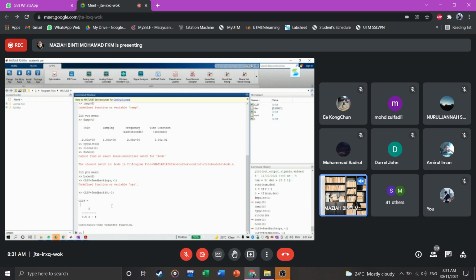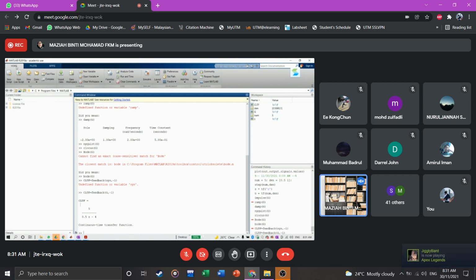So we can draw as if we draw on paper, and then we can simulate the behavior of the system. All right, so in order to open Simulink, you can click the Simulink logo on the top here, at the Home tab. Make sure you click on the Home tab. Then there is Simulink. Okay, you can click that one, or you can also type simulink.